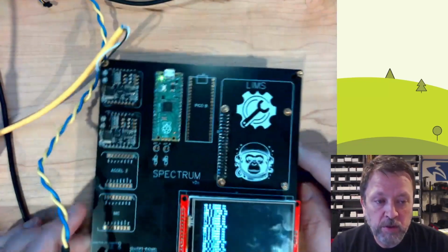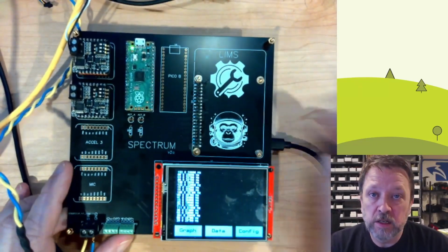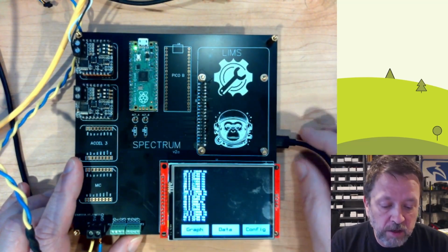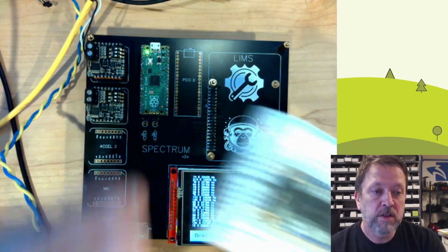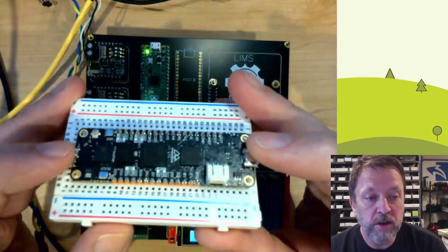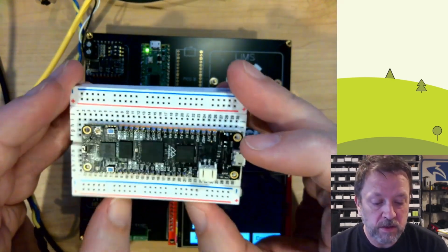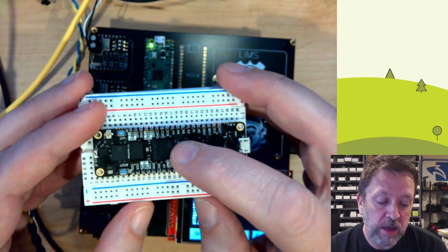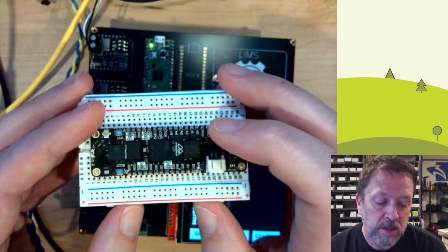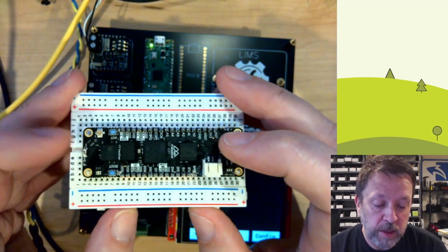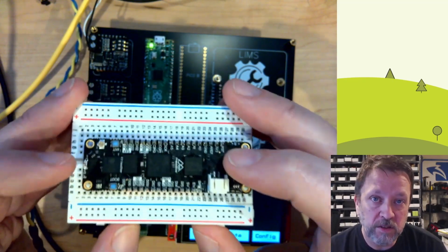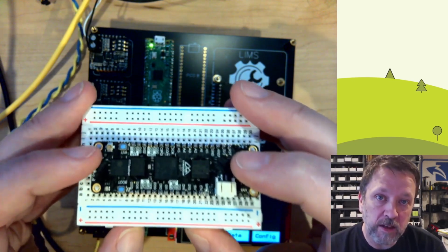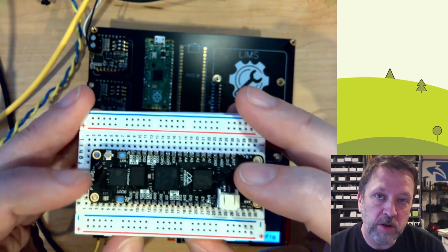What I ended up doing was building some custom hardware. And so I'm going to go through this and kind of how the development happened on this and the general pieces. First, I tried to run this on a Meadow F7 device. So this is the F7 Feather. This has a STM32 processor on it. This turned out to be able to collect data from a single channel at a rate that was fast enough, but it couldn't do anything else. So I had to move up to something with more horsepower.